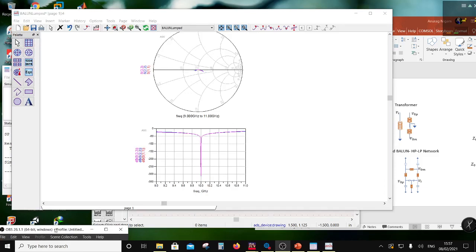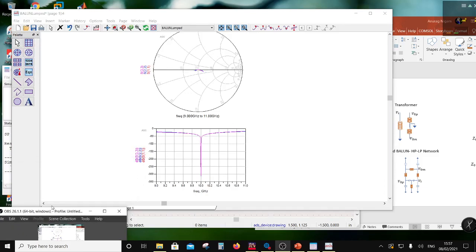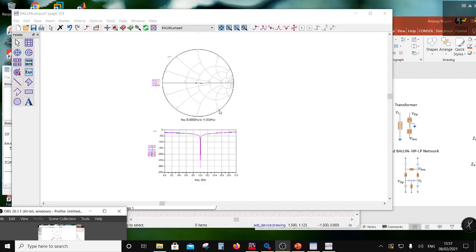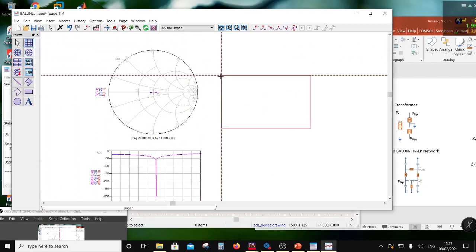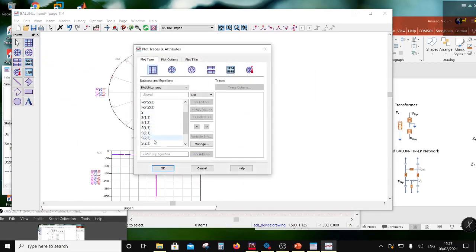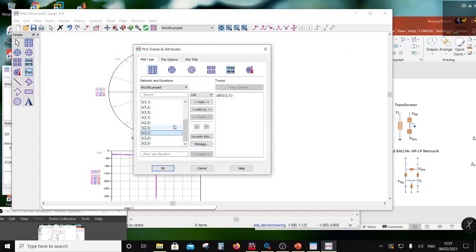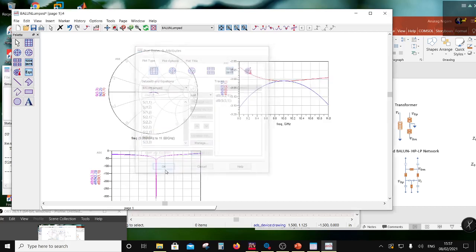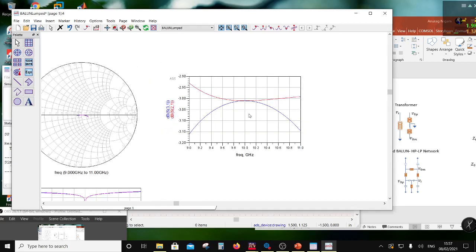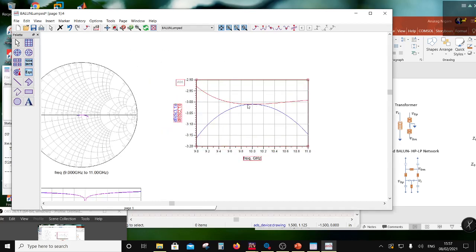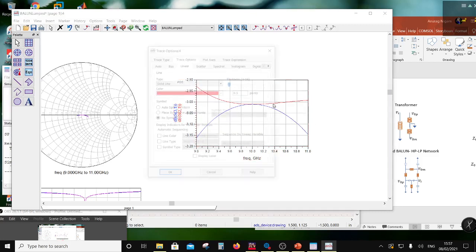Okay, so now that you have this, now we have to establish what happened to the phase. Okay, so S21 and S31 will be 3 dB because the power is dividing into half. S21 and S31. Okay, now notice that this is really narrow band because, beyond this you have the amplitude imbalance here, right? So on the two sides of the frequency you see the amplitude imbalance.